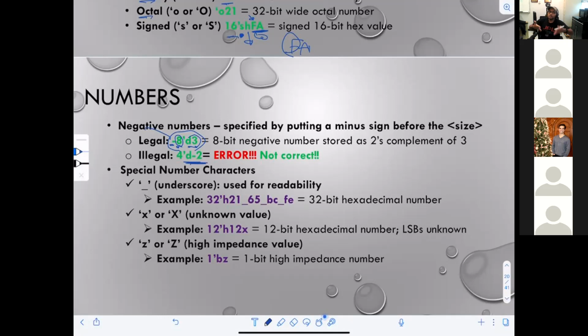Okay. Also, if you would like to make a separation, if you have a long line of number of bits, you can do it with underscore. So for instance, here I have a 32-bit and I would like to break them into parts. So I can make here 2 digits and then separation, 2 digit separation, 2 digit separation, 2 digit separation within 32-bit. Make sense?